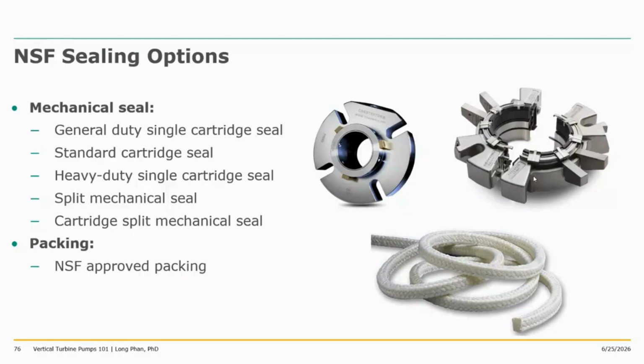The split one you see on the upper right really is a design for easy maintenance, right? You have the split design, so you don't have to pull the motor or pull the pump shaft. You can do the replacement of the seal more easily, with a cost.